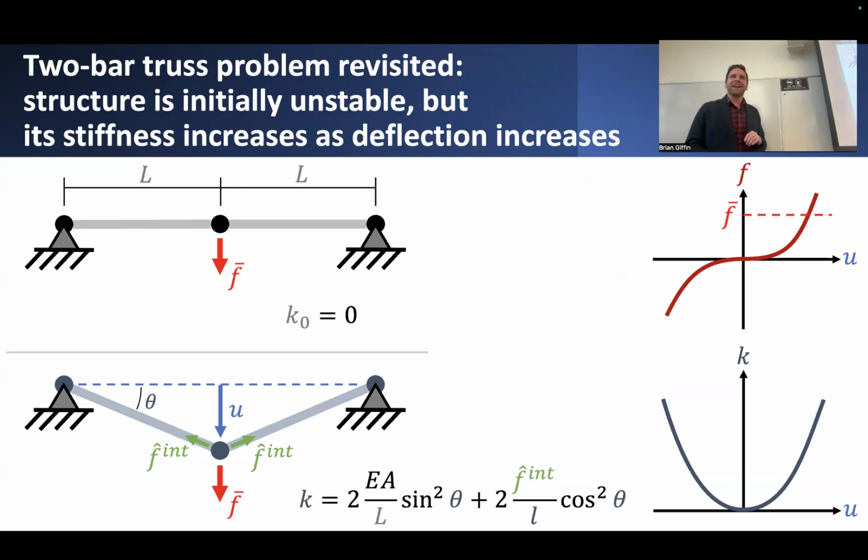But now, we have more powerful tools at our disposal. With the advent of these nonlinear expressions for internal force and these tangent stiffness matrix expressions, we can now actually solve this problem by considering the full generality of geometric nonlinearity. So what happens now in this scenario? We have this two-element assembly. We're applying maybe some transverse load to it, so we're pulling down on it.